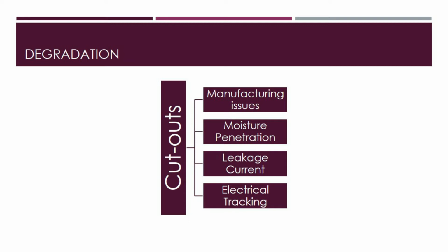A possible weak point could result from improper cementing, and during the summer, high temperatures can cause metal to expand and shatter the porcelain insulators, and the lower withstand voltages that come from damaged insulators can lead to failure. What's more, to prevent moisture penetration into the cement, paints or epoxies are employed as a sealer. Moisture may enter the insulator if the seal begins to break, and the porcelain can break due to changing environmental conditions, such as freezing and thawing, resulting in insulator failure.